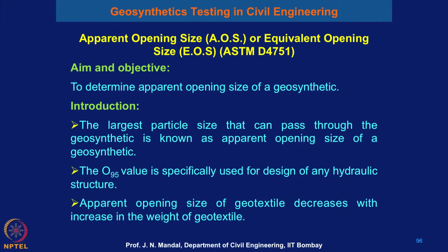So, next we will discuss the apparent opening size, or AOS, or equivalent opening size of the geosynthetic material. This is as per ASTM D4751, and it is very important. You should know how much quantity can pass through the geosynthetic material and how much material can be retained. It is exclusively used for filtration and drainage, and this is a very important test to perform.